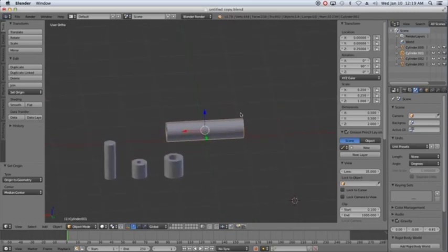Now I still need a hole through the middle for the main drive shaft to go, so I'm going to take my 3mm cylinder here, and I'm going to put it at the origin. So 0x, 0y, and I'll just leave it there because it's going through. And I'm going to poke a hole through this.